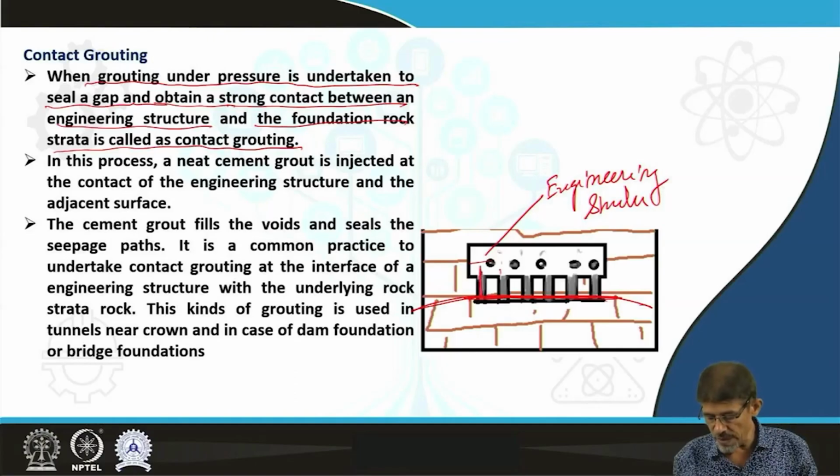In this zone we are going to create grouting holes and fill them with grout. If a single attempt at grout holes is not suitable, then we go for other holes near the contact zone of the engineering structure and rock strata.